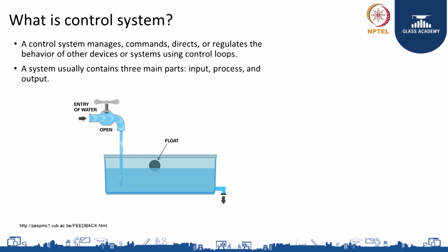So to maintain that level, we will change the intensity of the artificial lights and get the desired level. We can sometimes also change the angle of the blinds or put shades and control the amount of daylight that is entering into the space. So basically, we want to control and achieve a desired lux level on the task surface.